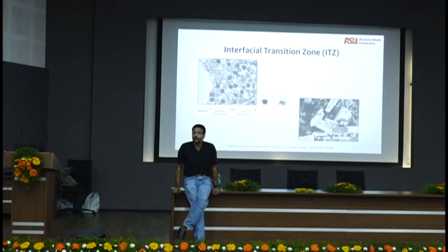Common sense. Tell me why would silica fume densify the interfacial transition zone? Not just consume CH. Even more important, what is formed first? CH. As soon as calcium hydroxide is formed, silica fume is there already. It will immediately consume that CH, and you will form CSH very quickly, right? So there is an immediate transformation. So these things can't go and lie on sand particles and create porosity. CSH is formed there, which is amorphous and fills in all the pores straight away and quick. And that is why silica fume densifies the interfacial transition zone.